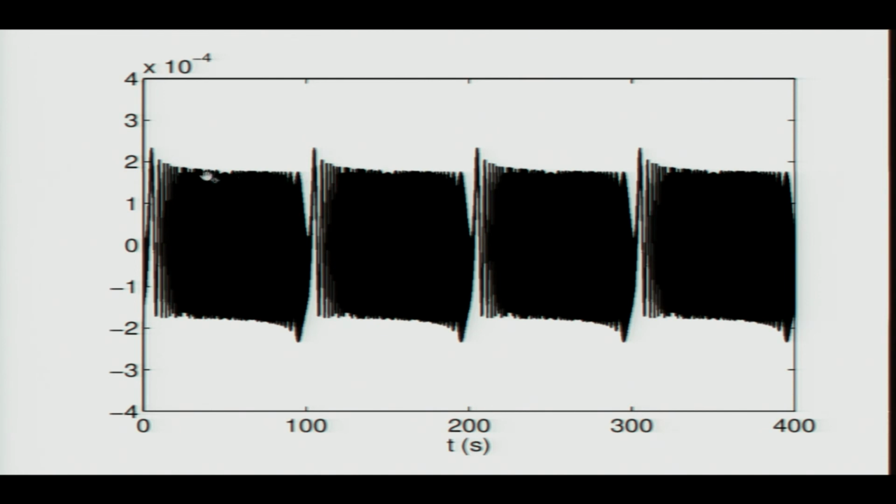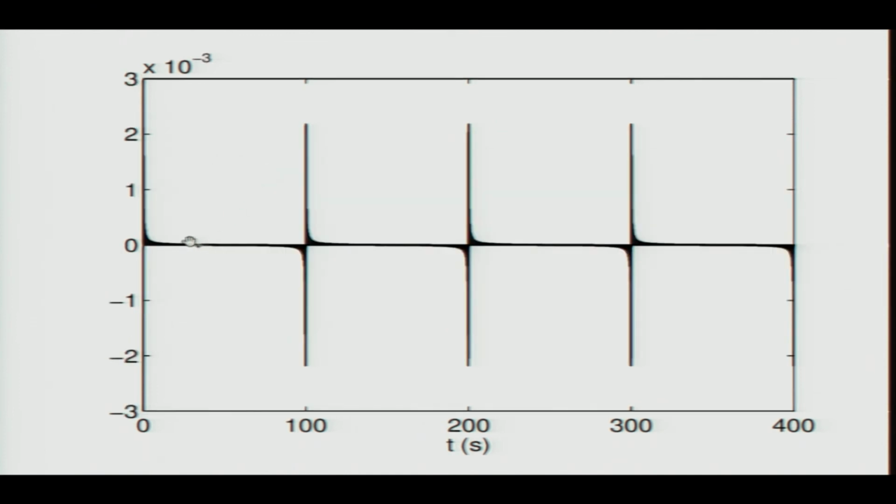Both these signals have the same frequency components, but what I have done in this particular signal is add up sine waves where all the sine waves do not have the same phase. In that case the summation comes out to be of a lower magnitude, whereas in the next signal, all the sine waves have exactly the same phase, but different frequencies. So then the summation comes out to be a peaky kind of signal, with a very large amplitude.